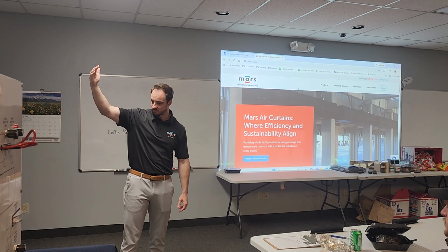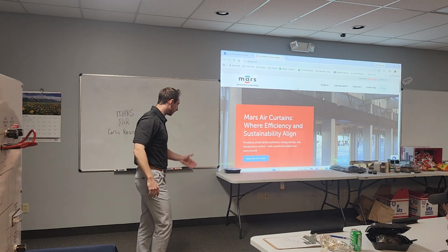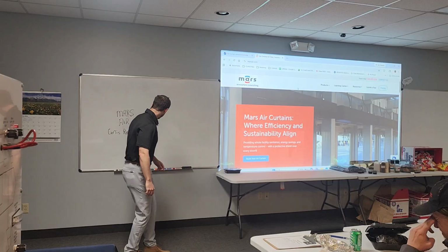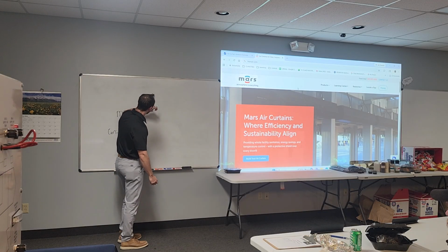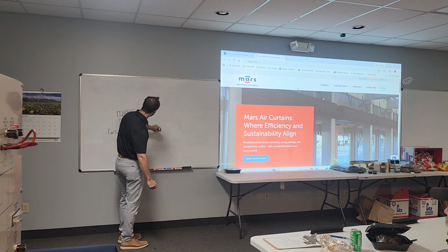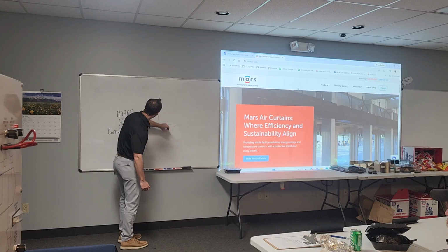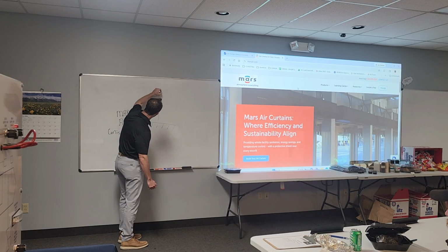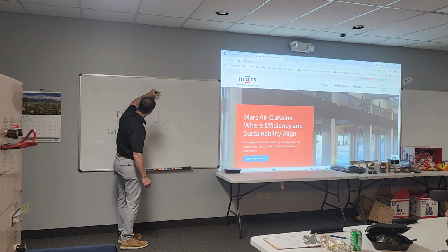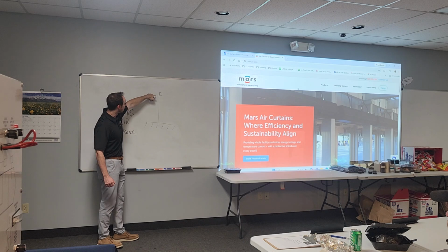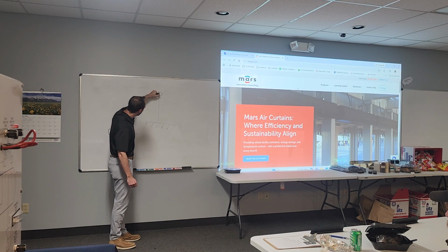Really, the idea is that the bottom of the airstream, I guess you guys probably can't see that, draws right on at the board. So let's do this. Okay, this is the unit. If we're looking at the door on the side here, this is the door, and here's the floor. And then here's the unit. Not an artist, it's not what I get paid to do. Luckily, I get paid to do the talking. So this is a typical application: here's the door, you want it right above the door, and it's blowing straight down.